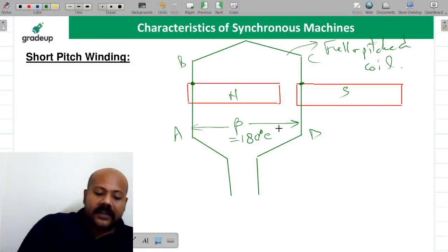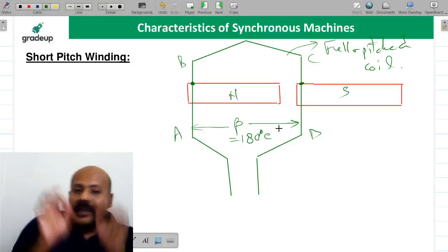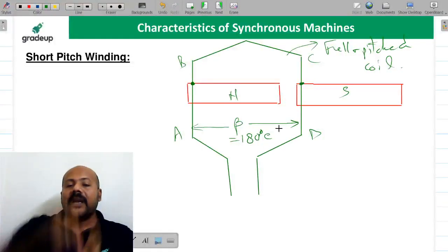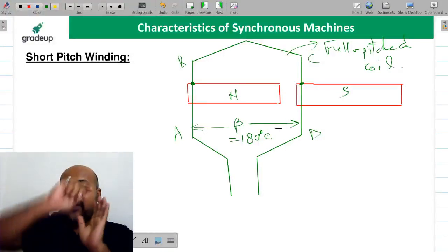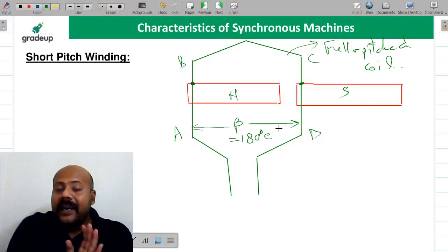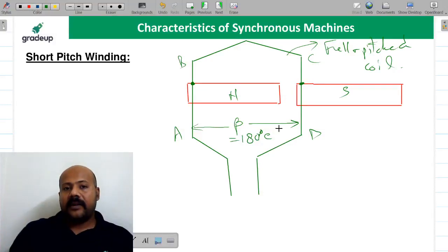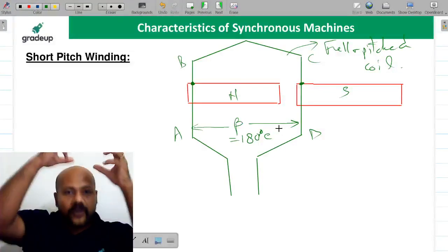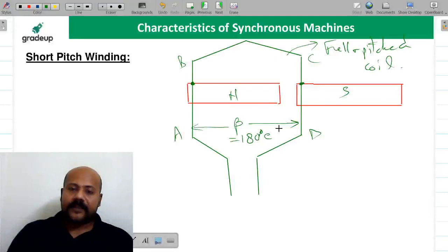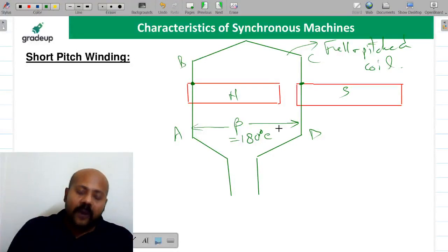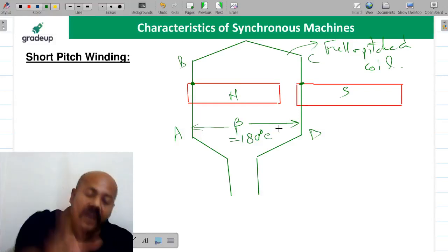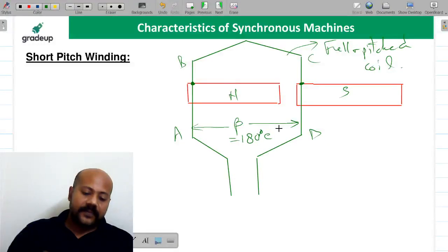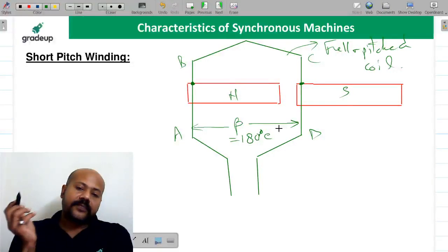Now Shankar Natarajan is asking, sir, it is actually slot angle. Now you listen to me, beta. Suppose there are a number of slots on the periphery. All these slots are going to be divided among three phases. If you are going for a three-phase winding, there is going to be A phase, B phase and C phase. So it is not just slot per pole, it is slot per pole per phase. That should give you 180-degree electrical. I hope you are getting this.